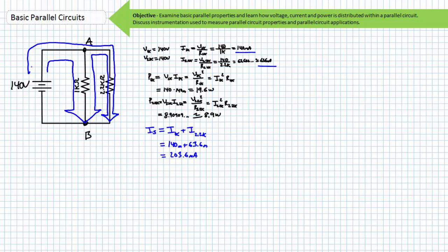Understanding Ohm's law and our newfound appreciation for basic parallel properties, we can therefore state that the smallest resistor will draw the most current and the largest resistor the least. If two identical resistors were hooked in a parallel relationship between two nodes with the same voltage across them, it stands to conjecture that the identical resistors in a parallel relationship will draw equal amounts of current.